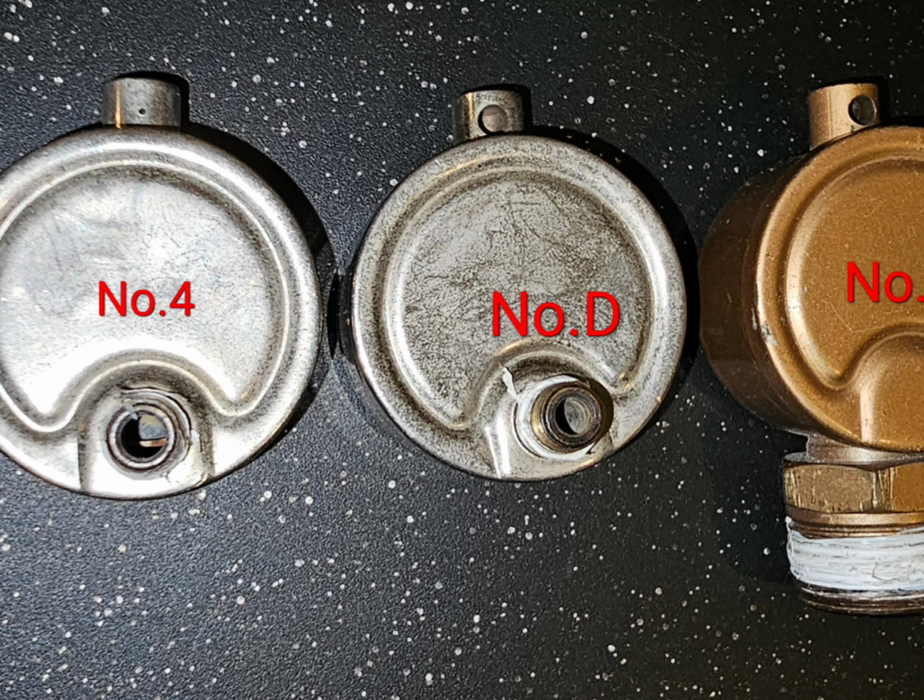But steel convectors, like I stated, once the call for heat has been satisfied and the heat shuts off, those radiators are going to start to cool down. And it's just based off of the way they're constructed. They have small steam columns or tubes that run through it, depending on how many tubes might be running through it. Might be maybe 3, 2, maybe 4, depending on the depth of the radiator.